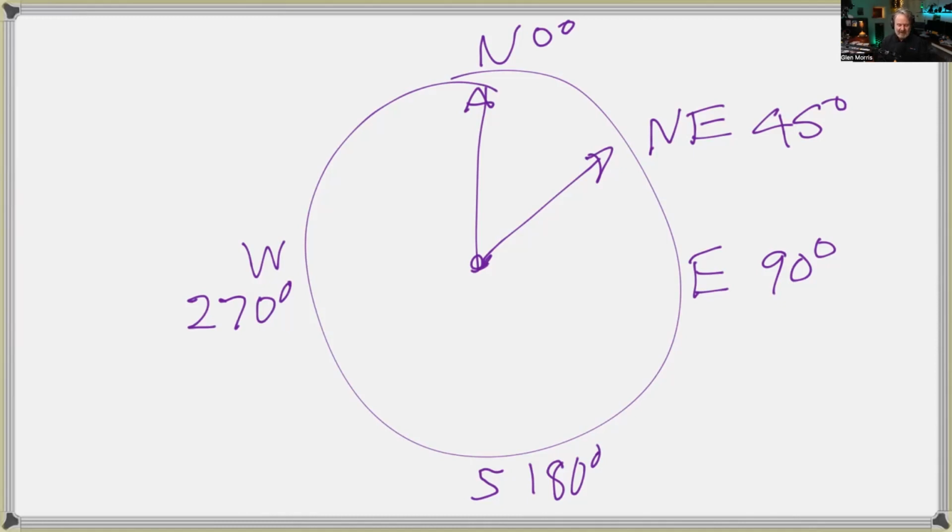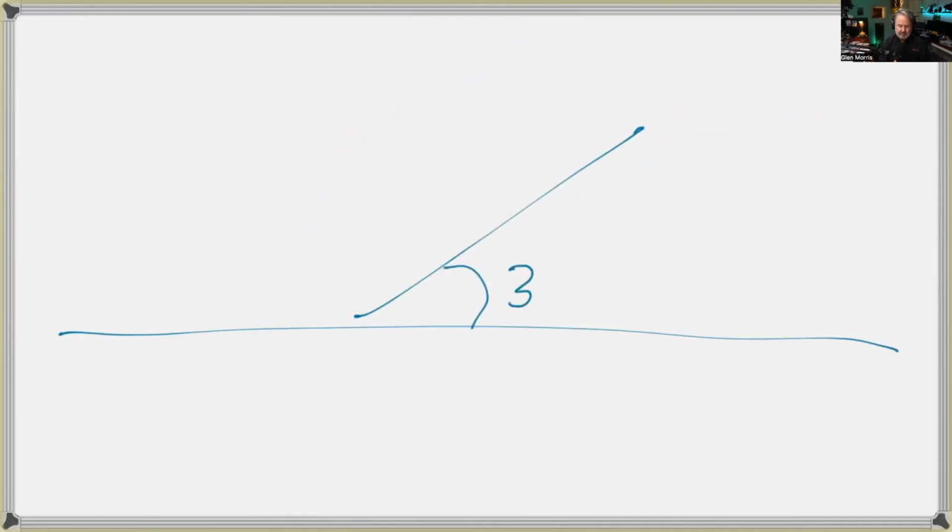There you go. The other thing that affects the solar radiation falling on a surface is inclination, and this is really simple. It's from horizontal. So there's horizontal, there's our plane of inclination, and there's our 35 degrees. So inclination. Those two things give you the key information that peak sun hour tables will be generated for.